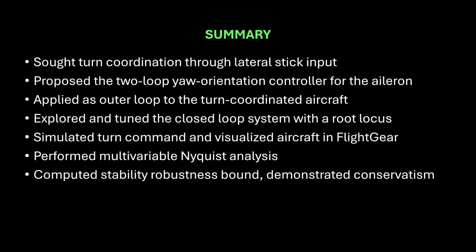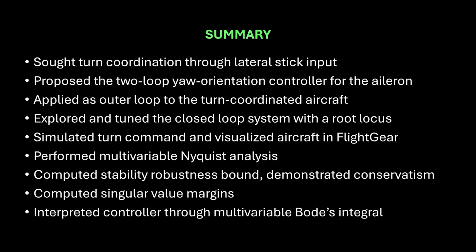it was quite conservative due to its assumption of an unstructured uncertainty. Singular value stability margins were computed and were shown to be below standard thresholds for single input systems, but were deemed reasonable given their conservatism. We then investigated the control system with Bode's integral, interpreting our tuned results in the context of a sensitivity volume that had been squeezed in worst-case directions.